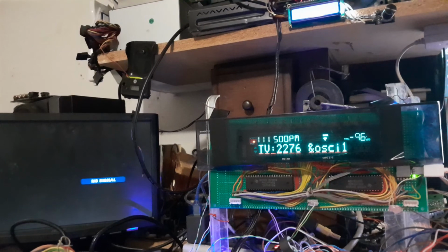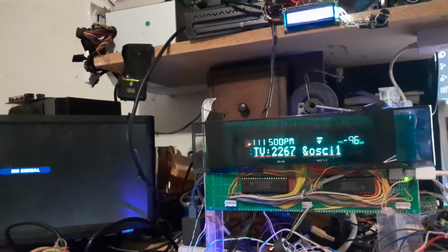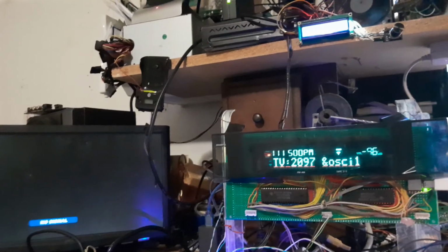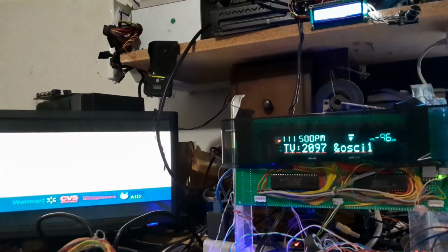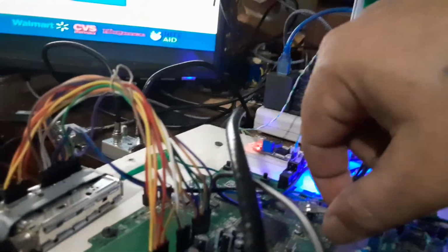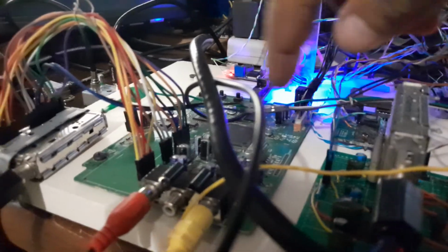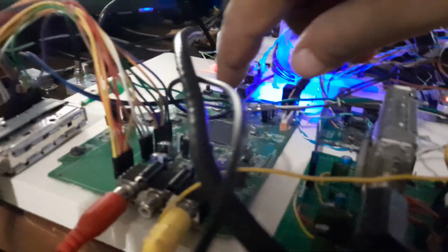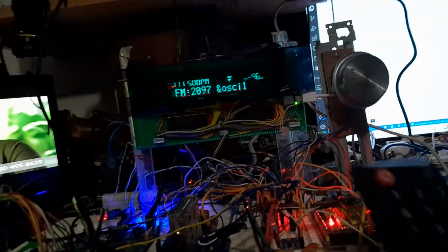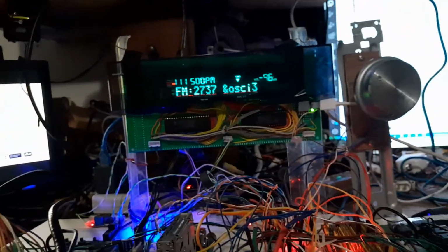What's wrong with digital TV? I'm not dividing right. I'm only controlling the digital TV through I2C, and the rest of the information is going to the board where I got it from the TV box. I'm only dividing the signal through the phase lock loop. But for the analog tuner, it was easy to divide. I go to oscillator number 3, up in frequency.